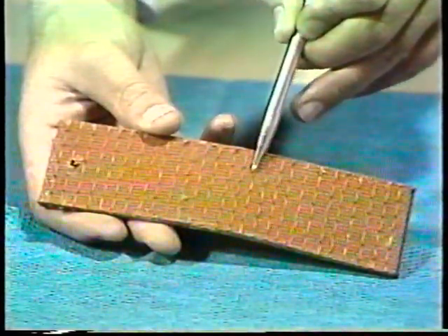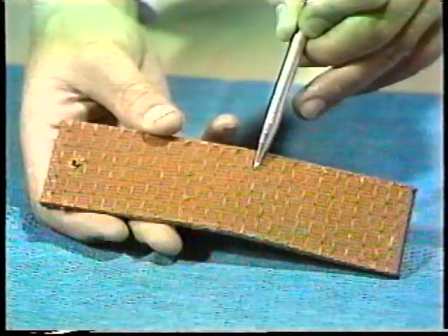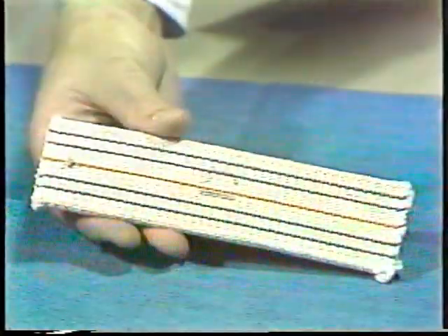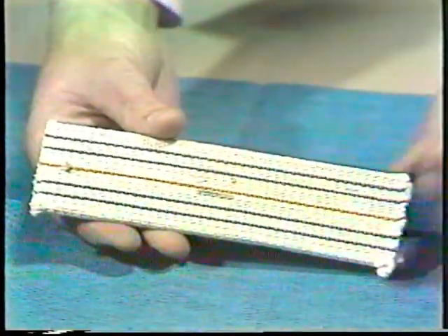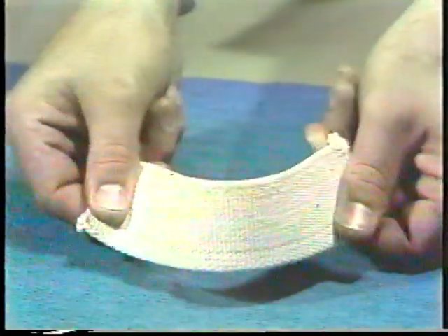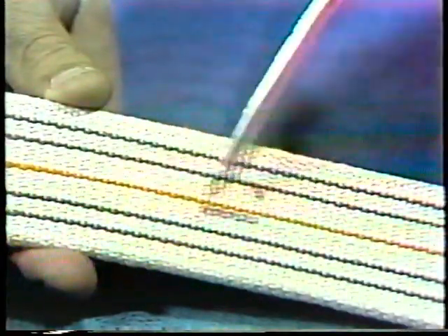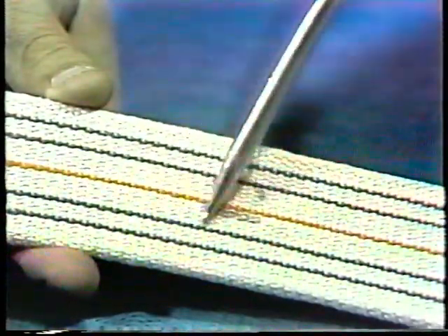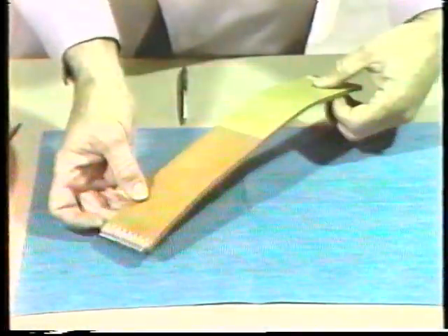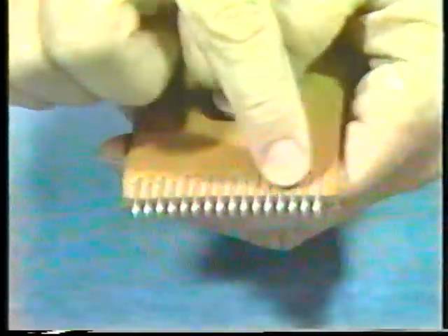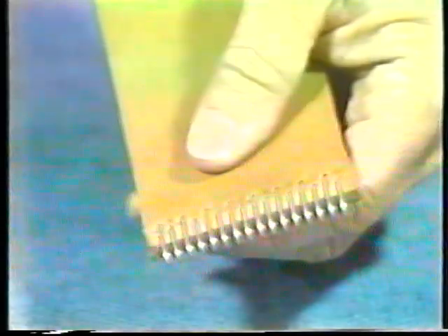Some belts are stitched for extra strength, although the rubber bonding is normally sufficient to hold the belt together. Another type of belt is the woven belt. These belts can be composed of cotton or synthetic material, either coated or uncoated. Usually they have stripes running lengthwise to indicate the number of plies in the belt, one stripe for each ply. The ends of both leather and cotton belts are connected by lacing the ends together or by fastening them with steel clips or wire hooks. Some need a special machine for installation, while others need only a hammer.